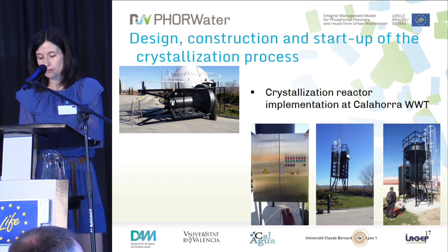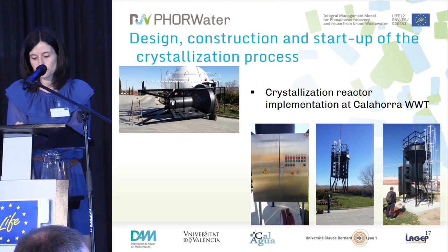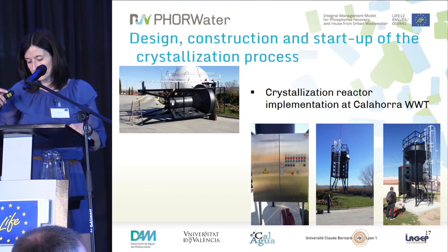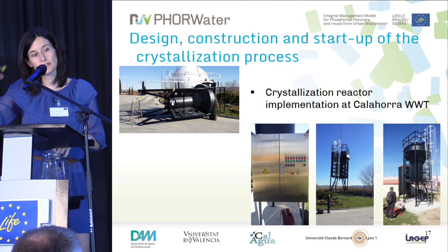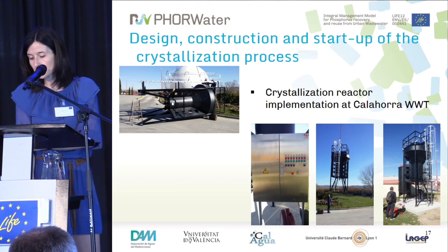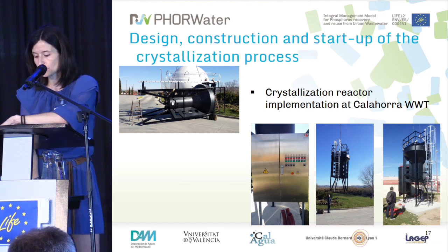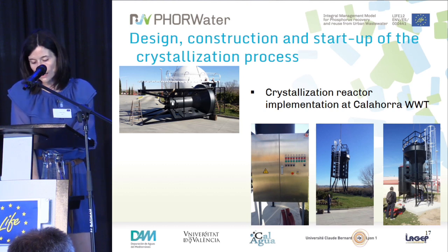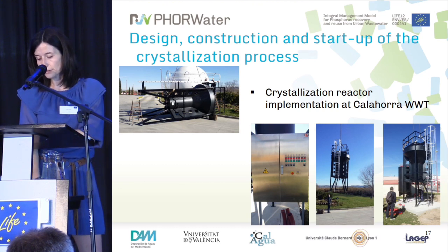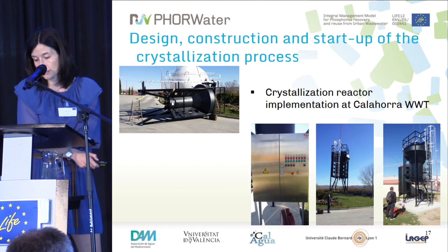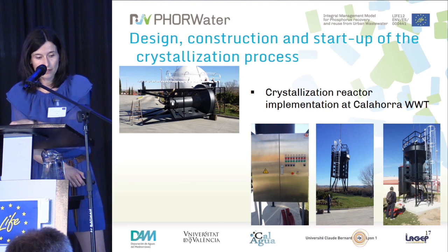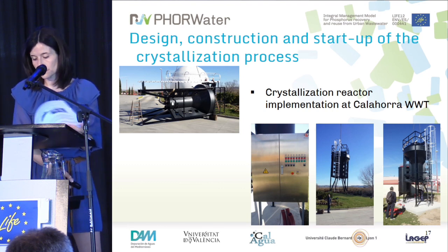Computational fluid dynamics simulations have been performed to determine the position of the inlet pipes, to determine the optimal position of the stirrer in the reactor, and to ensure that dispersion of the 3 inlet flows was efficient. It was also important to evaluate the supersaturation reached near the injectors, and actually the main steps in the design were the flow dynamic simulations.